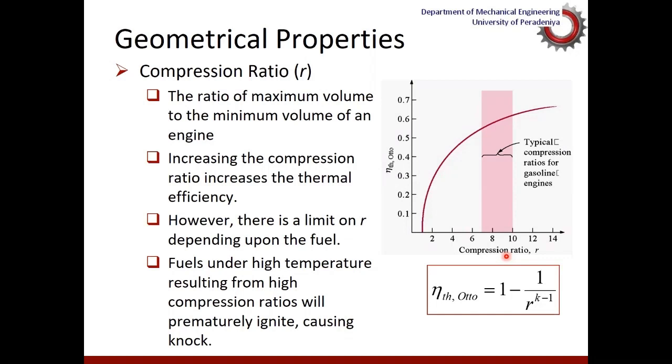Now in petrol engines, can you go for a very high thermal efficiency by increasing the compression ratio? When you look at this curve, you can go up to 70%, for example. Can you achieve 70% thermal efficiency by just manipulating the compression ratio? No. Why is that? Before we ignite the gases using the spark plug, the gases can start igniting on their own due to high pressure and temperature created by the increased compression ratio.